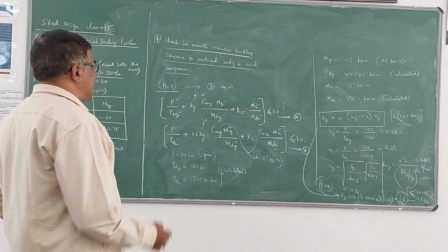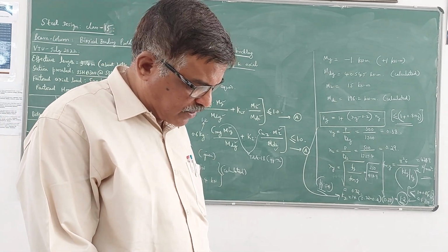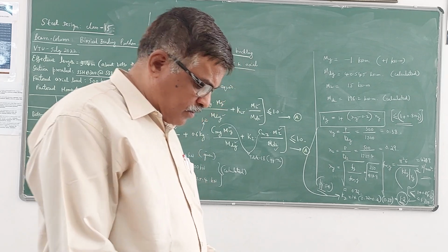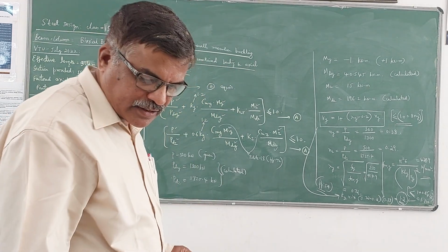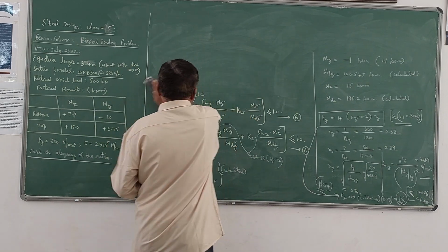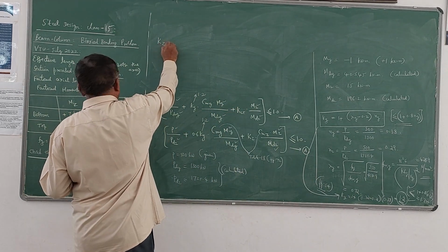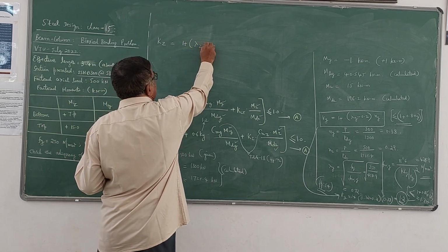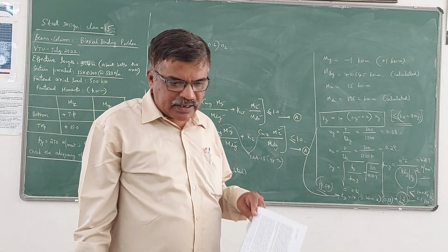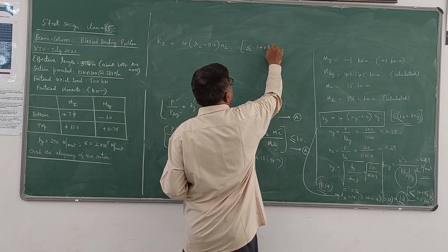Next we need to calculate this KLT, CMY and CMZ. So those three values we require. For that, we also need the value of KZ. Now similar to KY, we will calculate this KZ value. In the same page he has given another expression for KZ. For calculating KZ, the formula is 1 plus lambda z minus 0.2 into nz. And on similar lines, it should be less than or equal to 1 plus 0.8 into nz.